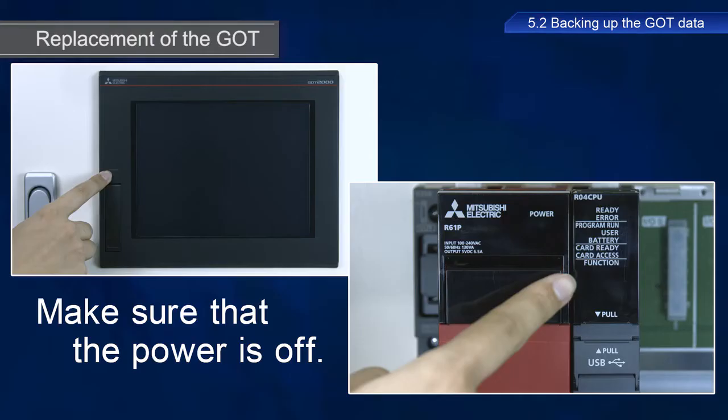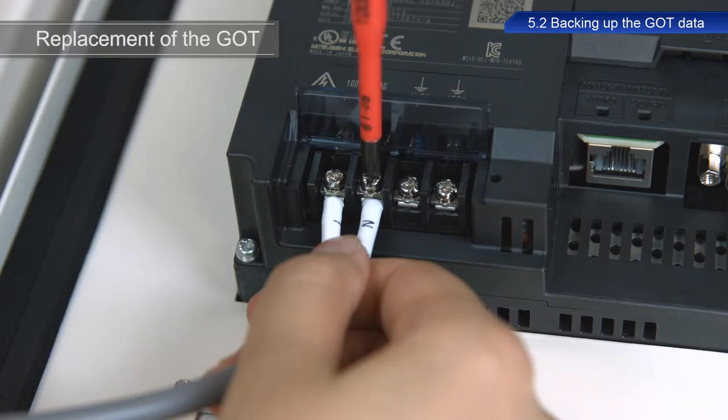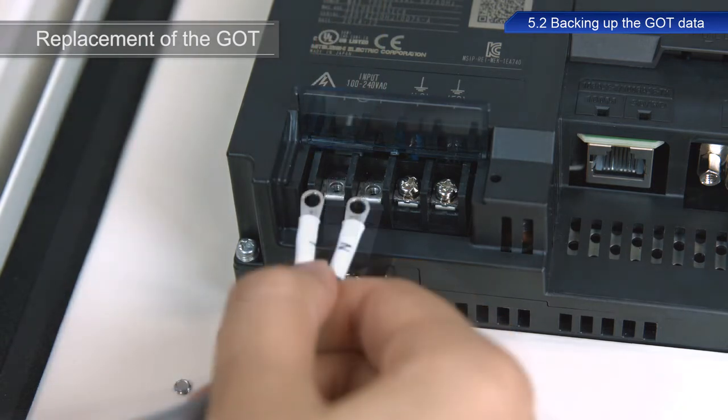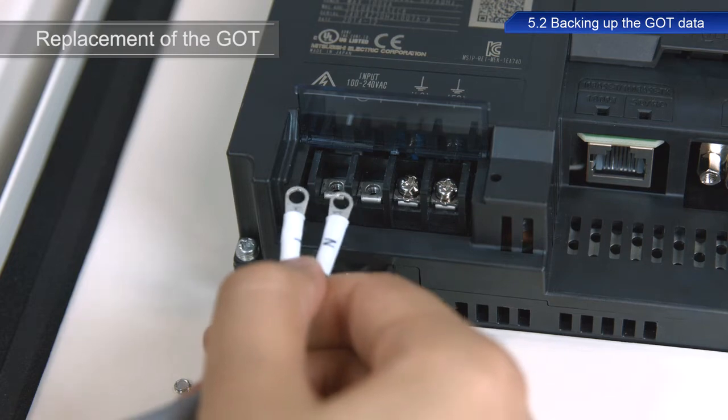Let's now replace the GOT, assuming that some accident has happened requiring replacement. For safety, you must turn off the control power before replacing devices. After confirming that the power is off, disconnect the power cables. For power cables, use these kinds of round crimped terminals with insulating sleeves to prevent short circuits from happening as a result of screws becoming loose.